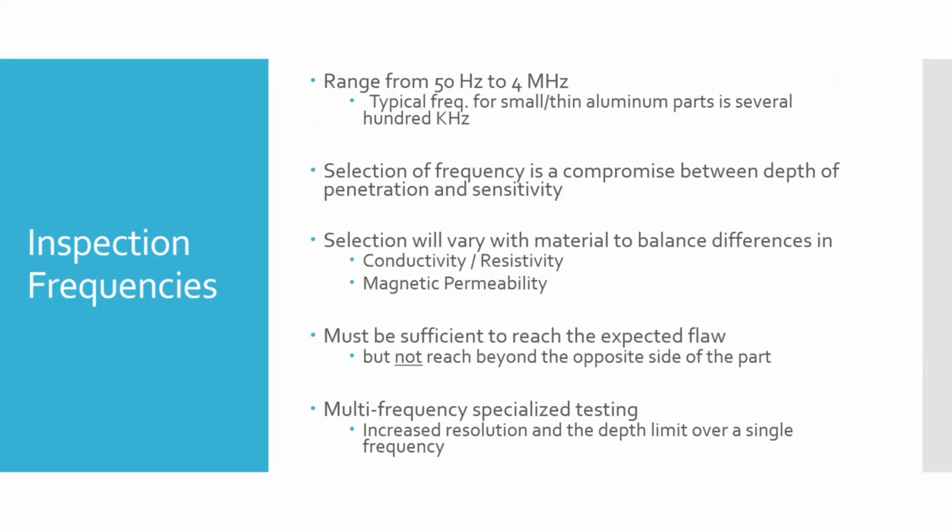And you're deciding, because you can't control permeability, because you can't control conductivity, your frequency selection is where you're balancing that depth of penetration versus how sensitive your probes are going to be. But if you're trying to say, okay, I know aluminum, I usually set up at a certain frequency, right? I set up at 400 kilohertz, for instance.